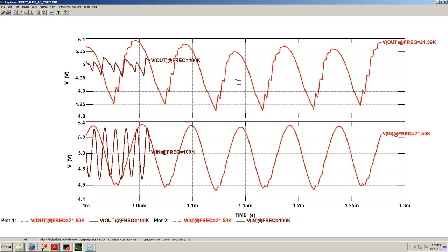So this is already distorted, meaning that I have too much signal here. And then you can also say the same thing here, that I have too much signal too. So basically what I get from this is at the low frequencies I want to pump a higher amplitude, and then as I go up in frequencies I want to back down on the signal. Okay, so how do I do that?